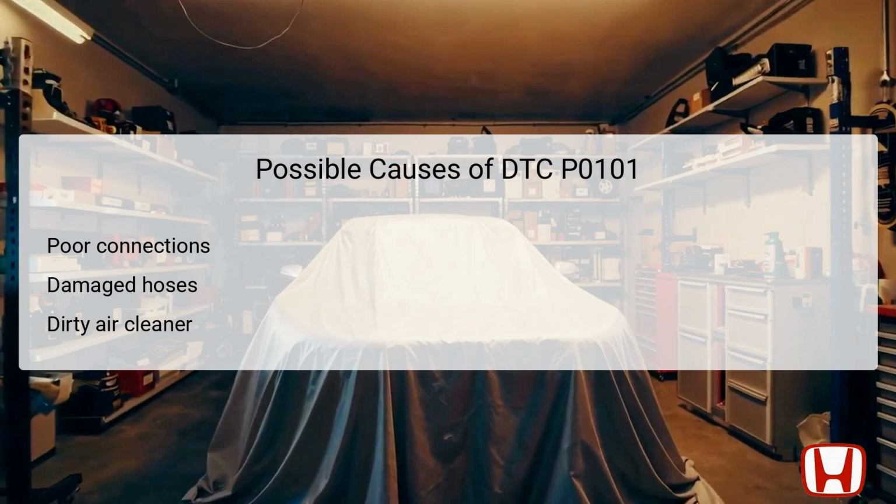Additionally, a dirty air cleaner can restrict airflow and produce erroneous data for the ECU, prompting the DTC to store.